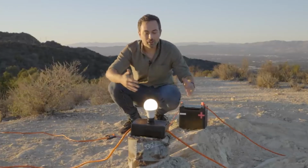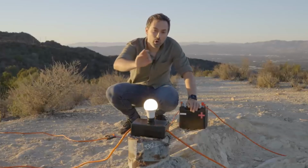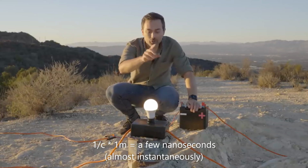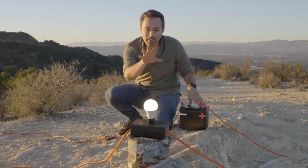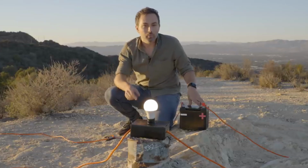The electric and magnetic fields can propagate out through space to this light bulb, which is only 1 meter away, in a few nanoseconds. And so that is the limiting factor for the light bulb turning on. Now, the bulb won't receive the entire voltage of the battery immediately. It'll be some fraction, which depends on the impedance of these lines and the impedance of the bulb.